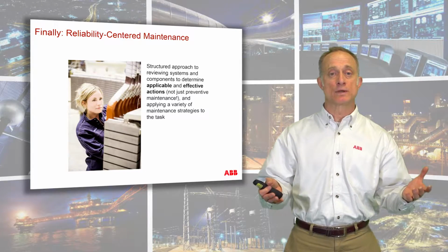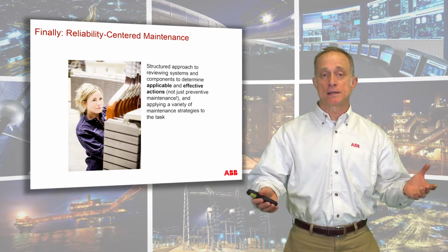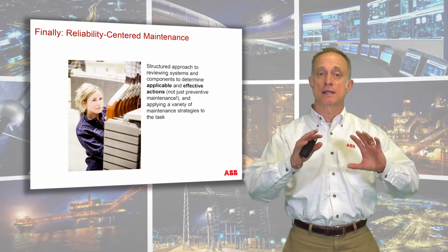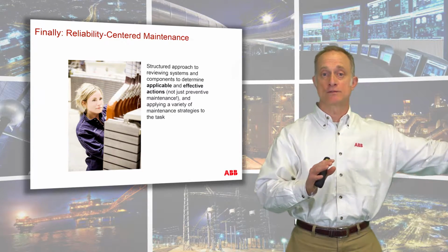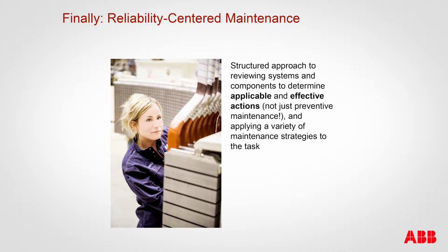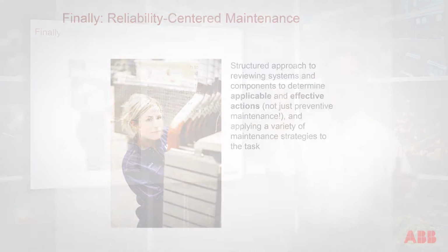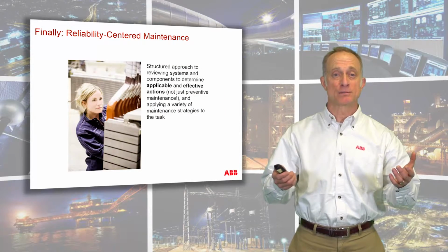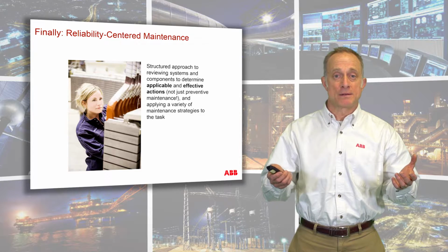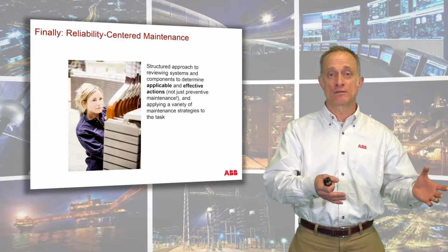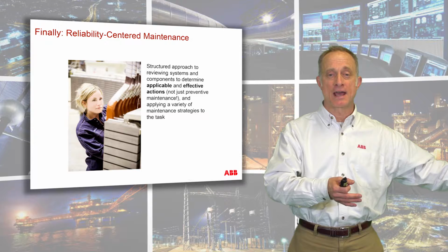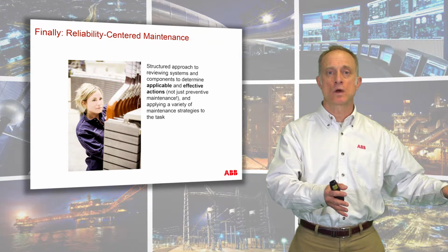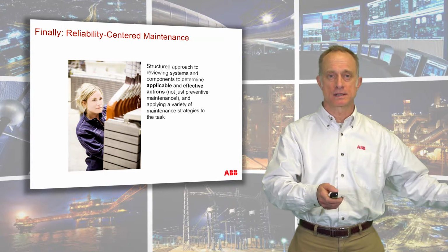Then finally, we get to reliability-centered maintenance. And as I mentioned before, reliability-centered maintenance takes advantage of all of those things and only chooses the right approach for the right piece of equipment. Even reactive maintenance. Or a strategy might be to not choose any maintenance approach at all. A right strategy might be to just let a piece of equipment run to failure. If it's low cost and you have a hot spare, maybe it's just too costly to try to touch that on a regular basis. Let it fail.